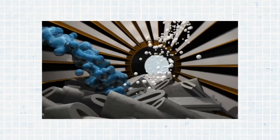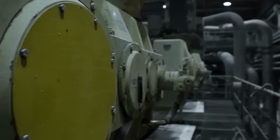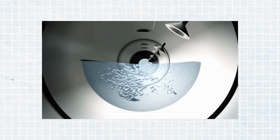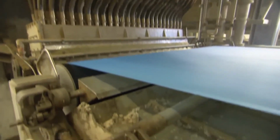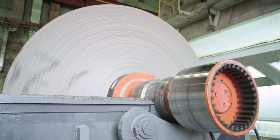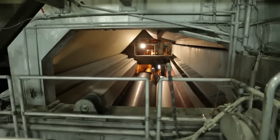The prepared pulp is poured onto a belt or net, where the water is drained away, leaving a layer of fiber. This wet sheet then passes through rollers that further extract the water, increasing its density. It is then dried with heated rollers that evaporate the remaining water, resulting in a continuous sheet of paper. This sheet, although nearly complete, has creases that are removed with the use of ironing rollers built into the machine. Amazingly, this entire process takes only 7 seconds in real time.